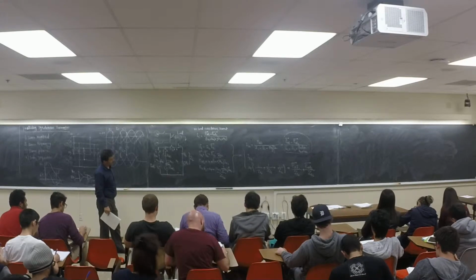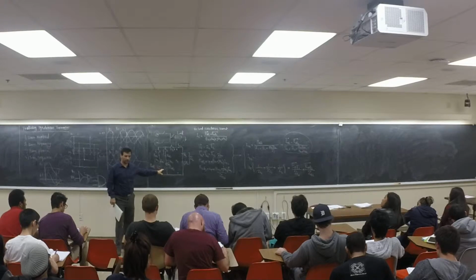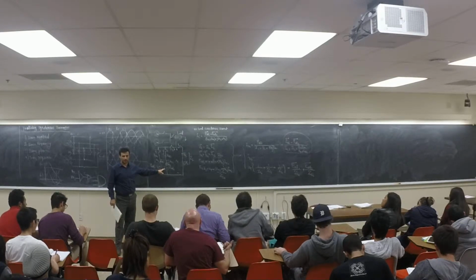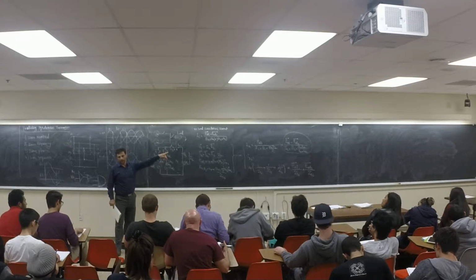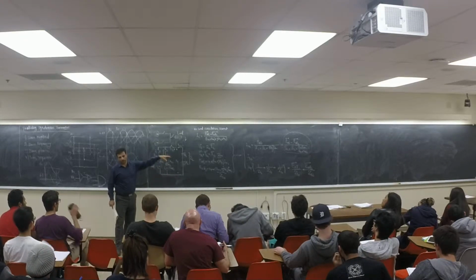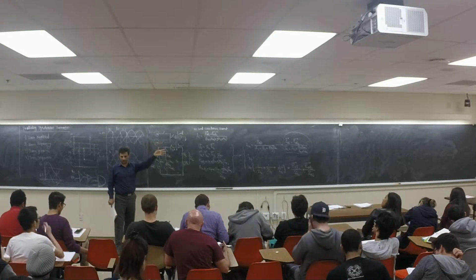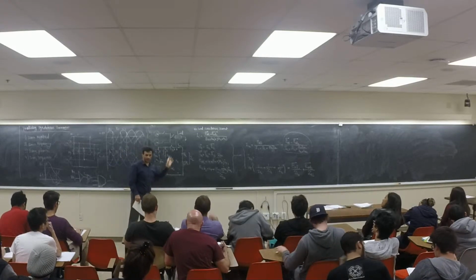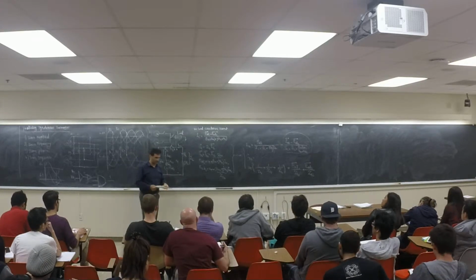So these are how you can calculate the power of this one. You have the EAF, right? And you have the IA. You take EAF times IA conjugate, and the power comes from there. It gives you how much P and how much Q it is giving you. The same thing for this one. You can calculate how much P and how much Q they are giving you, right? Let's go through one example.